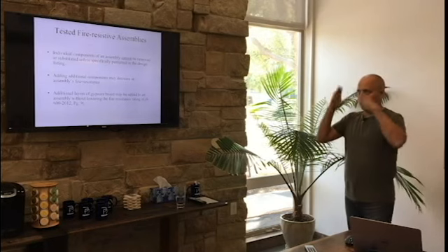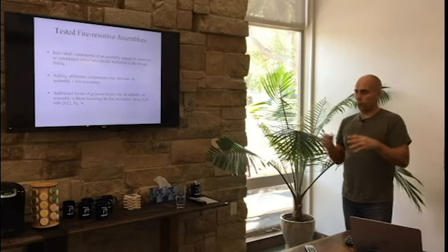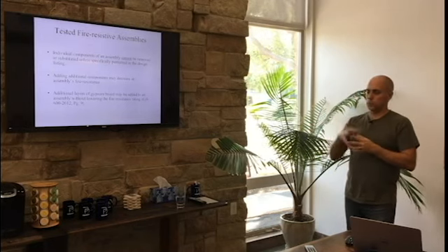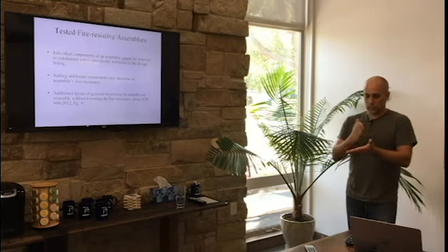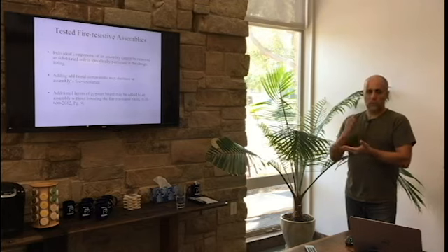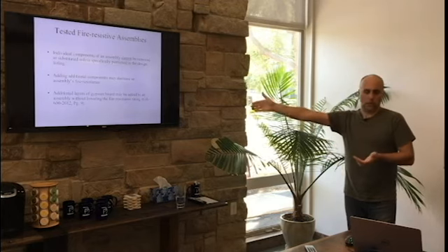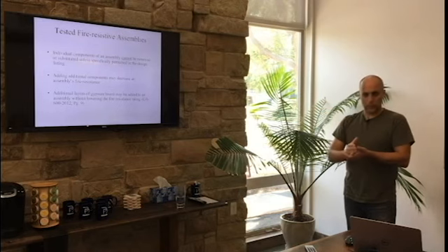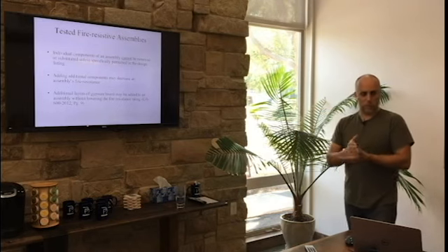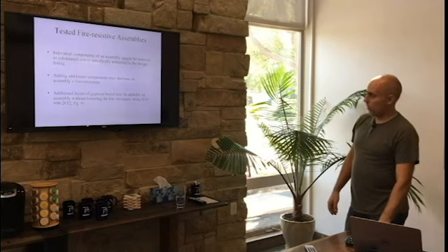So let's say P522 or P544, which is a typical roof ceiling assembly. It lists 4 different gypsum boards, 4 different products. That's what they tested it with. They didn't test it with another company's gypsum board. You can't use it, plain and simple, because that's what was tested. That's what's in the assembly. That's what you use.